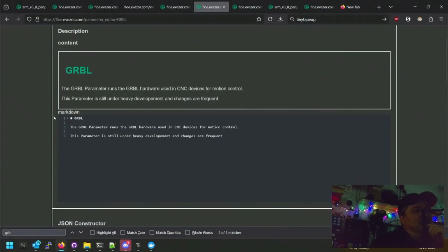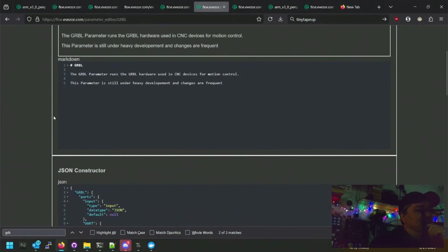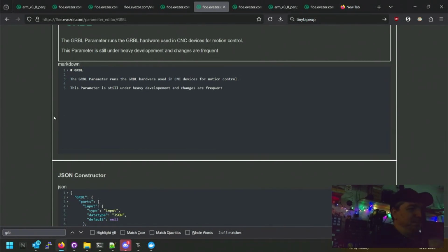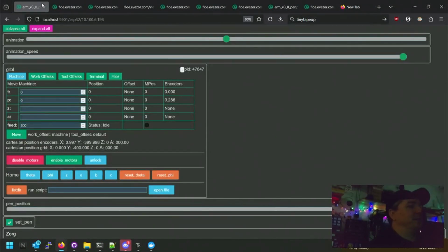This fits into a 40-pin DIP. I'm running out of pins more on the MicroPython side than I am on the FluidNC side, because you also have your shift register output.